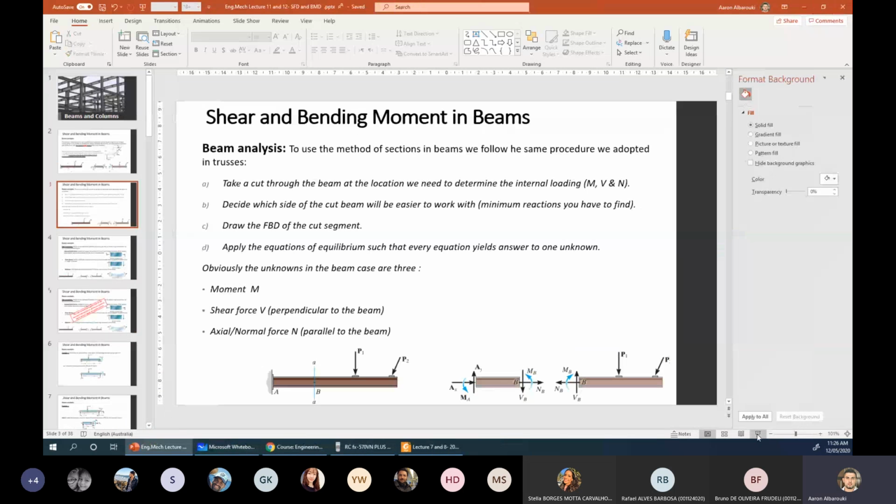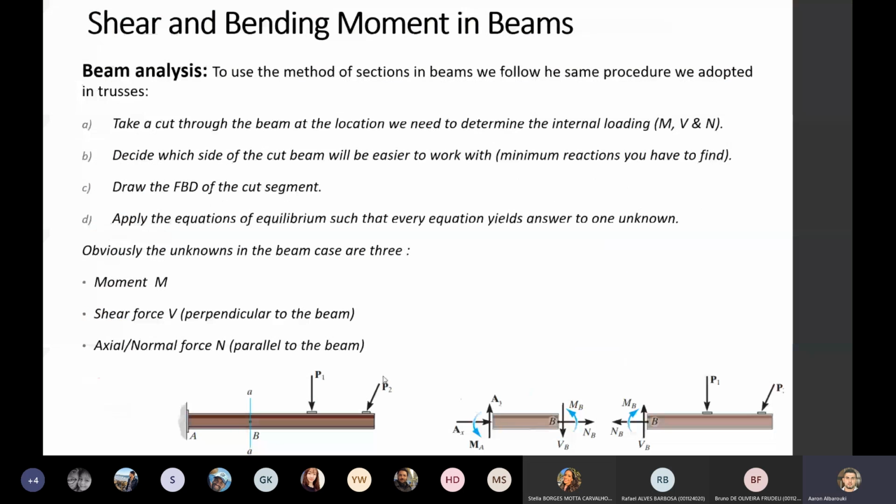Going back to our lecture. The type of support here is a fixed support, because that's the only type of support we can provide for a cantilever beam. Okay, so going back, if we need to analyze a beam, we agreed to take a section at that point. Before we do that, we have to change our beam to a free body diagram. We can't keep supports like this. We have to represent these supports with their reaction forces. Therefore, this is a fixed support. It will provide 3 different reactions. We'll put the reactions in there.